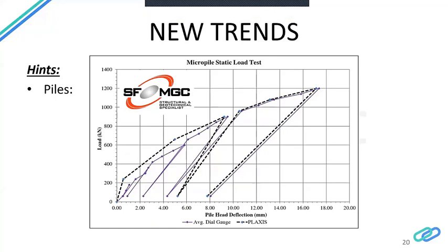And with this pile load test, you might get the advantage of using the embedded beam elements in the finite element modeling rather than the volume elements, because you can estimate the end bearing capacity and the skin frictional capacity of the piles, which is an input for the embedded beam elements.